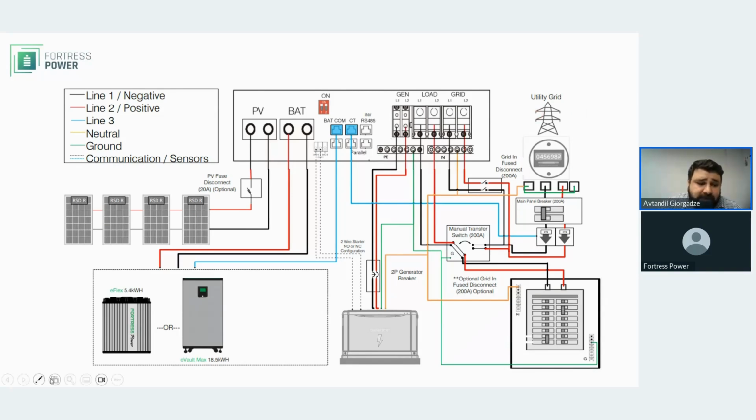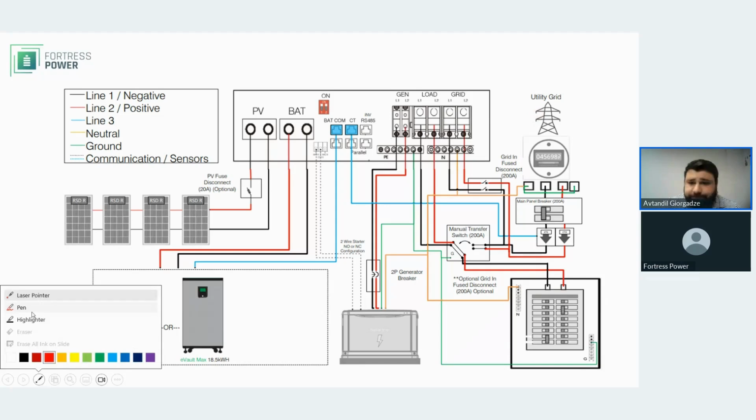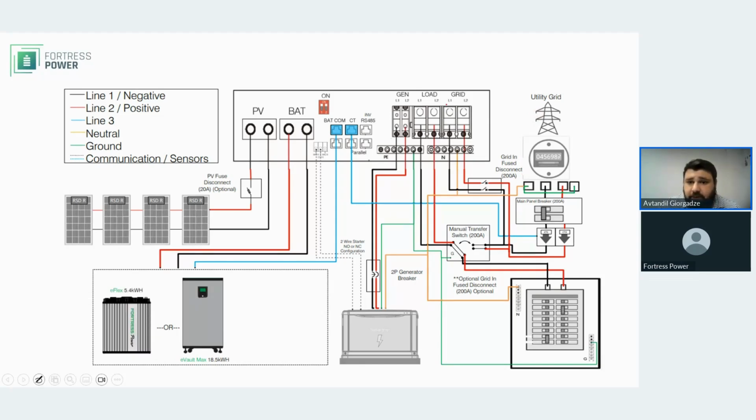But the moment when the grid outage occurs, your connection right here is interrupted. So you're not connected to the grid anymore. You will see no voltage here when the equipment detects the grid outage. Then your batteries, your PV, your generator, if it has to come on, will send the power through the load ports to the main electrical panel, but nothing to the grid ports, because the anti-islanding device, which was facilitating the pass-through, interrupted the connection.